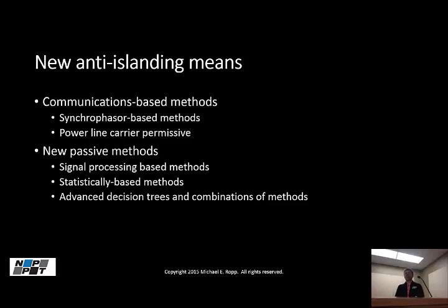We have worked a lot with subharmonic power line carrier for this application. We used Hunt Technologies' Turtle system for a while, demonstrated that it worked for this. There is a high-frequency solution also made by a company called Grid Edge Networks that is very intriguing because it's got a different cost trade-off. The problem with the subharmonic systems is that the signal generators are very expensive and require a lot of substation engineering because they're big and they have to go in the substation.